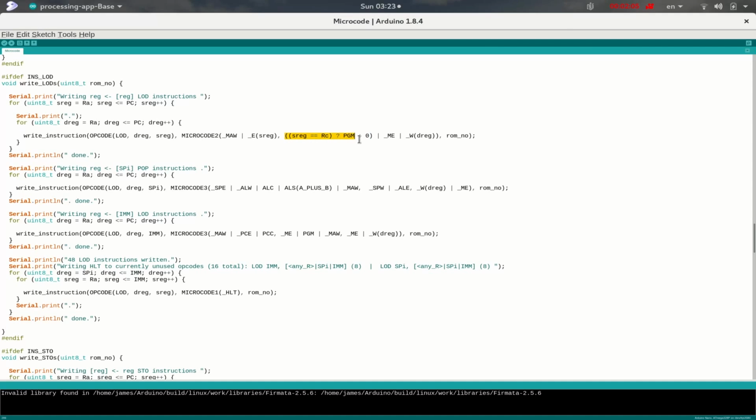Now, to get back to this little operation here, in general, this instruction is used to read data memory. But there may be particular circumstances in which you will want to read a byte from program memory. Now, of course, many instructions do that automatically. For one thing, the fetch cycle always reads from program memory when it goes to get the instruction. And of course, any instruction which is referencing an immediate operand will also access program memory, because immediate operands are located in program memory inside the program text.